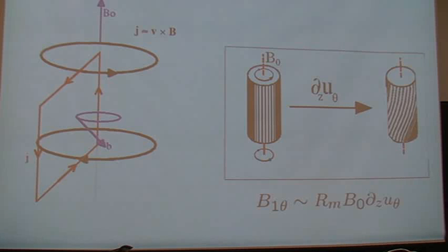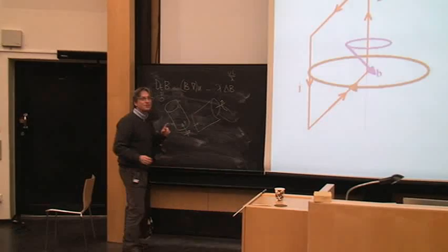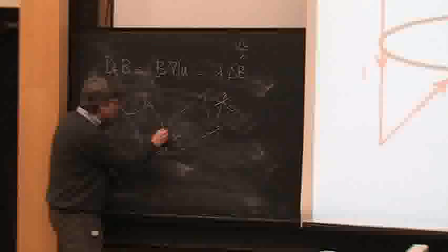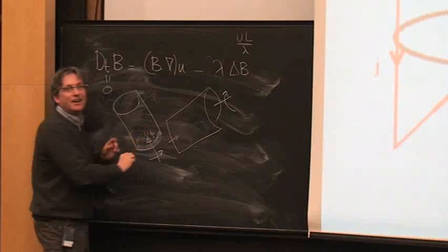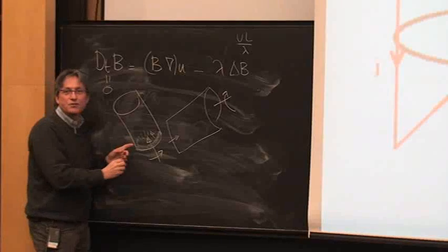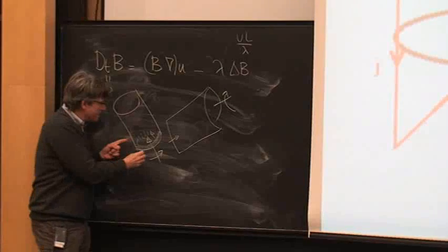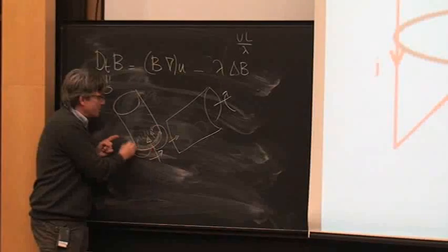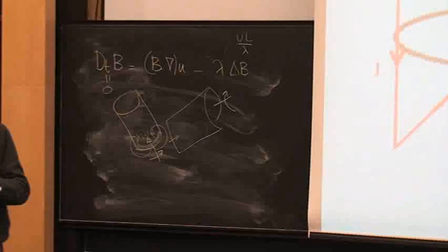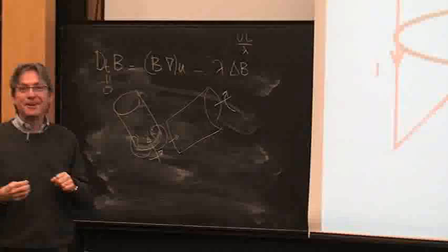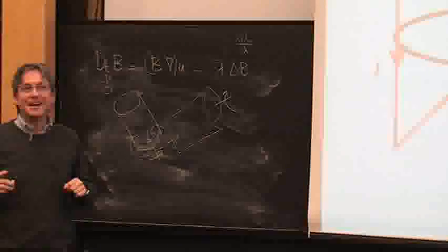There are many things about the dynamo that make it a fantastic example to study both from the theoretical point of view and also from the experimental point of view. It turns out that it works experimentally only because there's a piece of tape here that prevents the currents from looping back right where they started, and then they have to do this in order to produce the toroidal field. If you don't put the little piece of tape, then the threshold is higher.